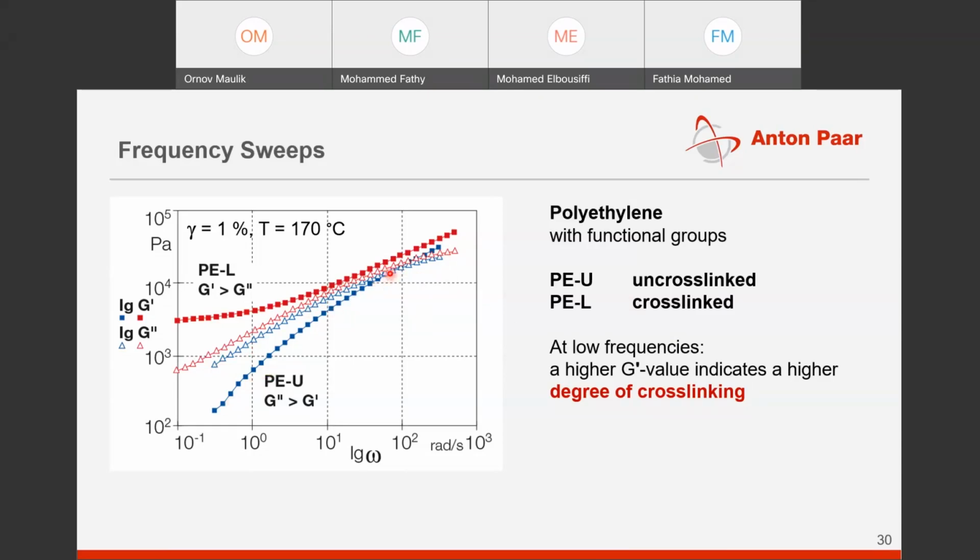So here you can say that this crossover point is the relaxation point of this polyethylene sample, and you can say that this much amount of time has to be given to this polyethylene in case you are using it for extruding or you are developing any particular polyethylene product. So this relaxation time information is really very crucial for polymer processing and polymer manufacturing.